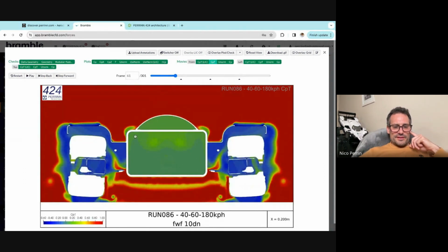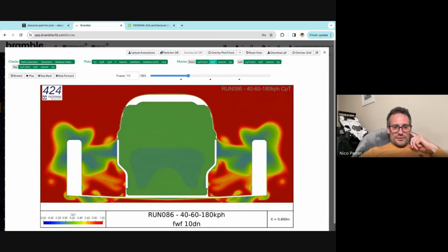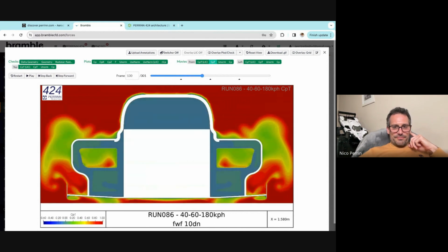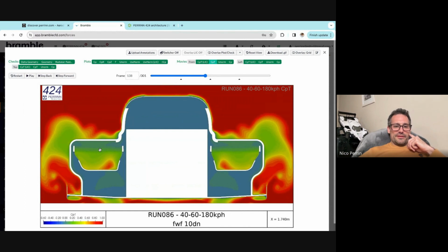Okay, you can see how that rotation has taken some of that wake with it. Okay, and then I can continue. Okay, now you can see the air coming inside the radiator. First of all, the air going inside the car will always be much slower than the air outside the car. It's a ratio of about 1:4 or 1:6. So 4 or 6 times slower the air going inside the car, just because it's going into an area of high pressure and slows down quite quickly.